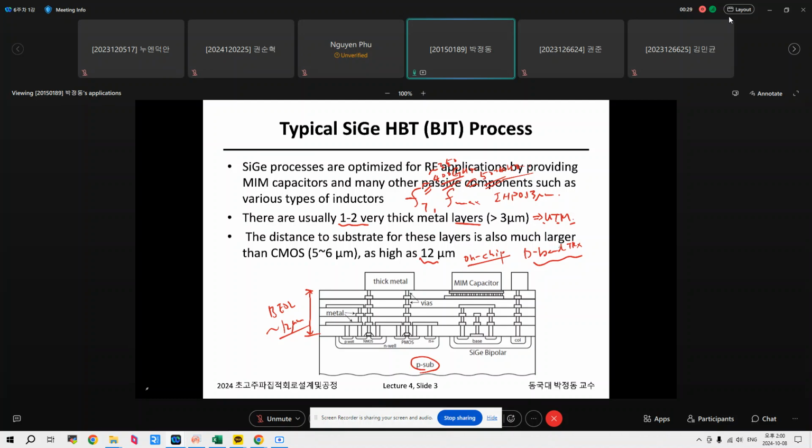If the thickness of the substrate is thin enough, then this looks like a capacitor. Okay, since it is a capacitor, all the energy is confined inside of this dielectric material, because the electric field between the two is too high to radiate.